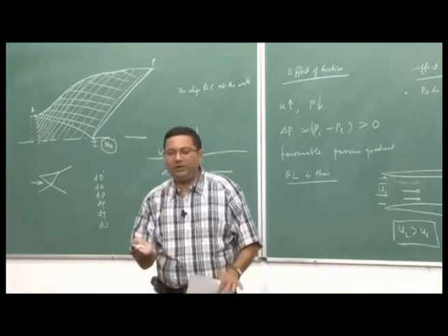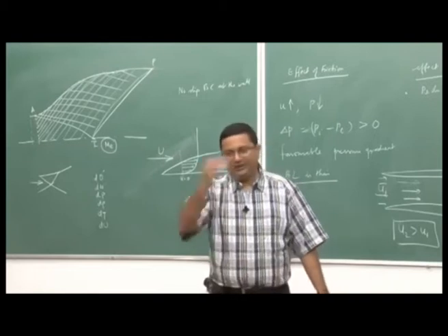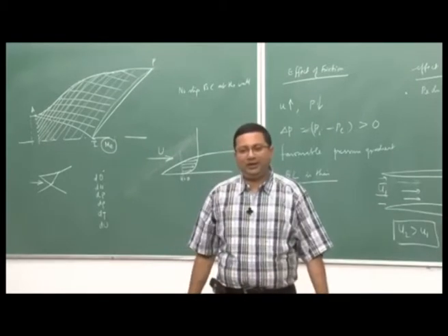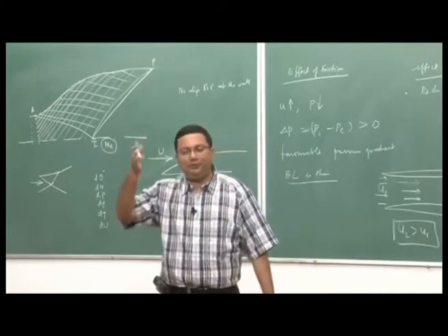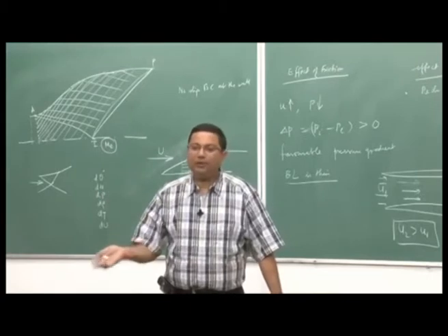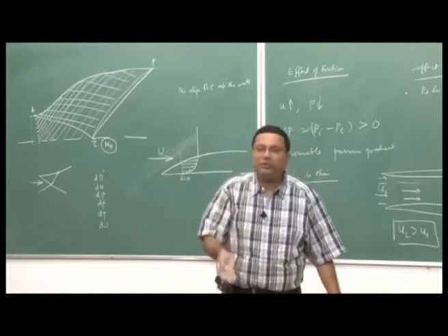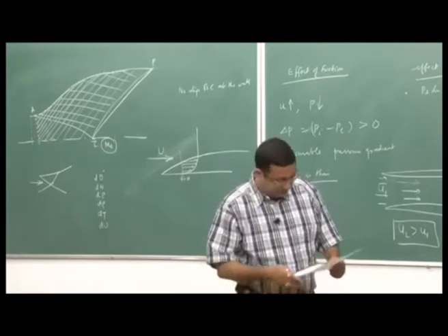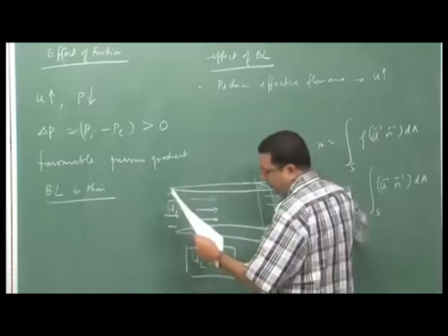Now, you have designed for a given Mach number or given velocity, which has now increased because of the presence of boundary layer. So, it is no longer going to exactly follow your calculations, therefore, your theta requirement is different, but theta you cannot change. So, the net effect will be all the flow properties are going to change. Okay. So, this is one of the effects of boundary layer.